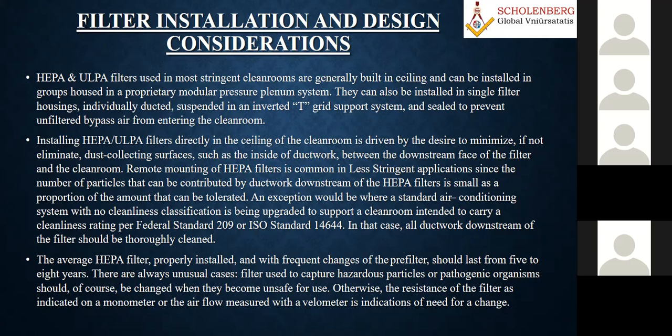You have to explain to the architect, look, my operation theater is here, and I have this much limitation of length. So you don't give me my plant room, which is another, say, 500 or 1,000 meters far away. And if I put these HEPA filters, I have to put the HEPA filters locally at the local hood. Or you have to give some local shaft where I can keep it there. Then when you provide the local hood, there should be an access also to go there.